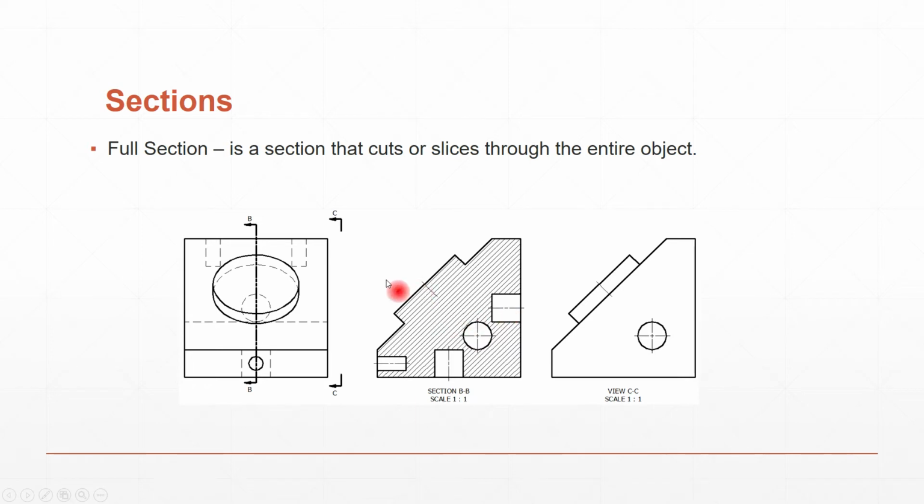Another thing that you will see is that sometimes people will cut a full section that's not going through any other parts, and that's nothing more than showing a view. It's a projection view of that right side, but it's shown as a view, and the benefit of doing this is so they don't have to line up. So if you put a view on something, you can put that view somewhere else. If you just do a projection off of an object, it has to be lined up next to it. So those are the two benefits of using a full section.